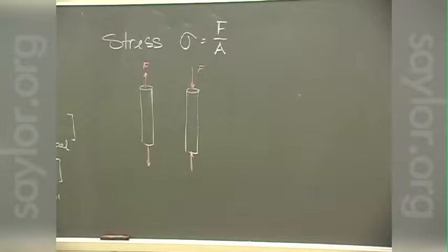For example, wood. Wood is very good in compression. It's terrible in tension. It's a factor of somewhere around 8 to 13 difference. If you're building something, you typically don't want to hang it with wood structural members. If you're going to build a shelving system that hangs from the ceiling of your garage, you're going to want to have it hang from chains or cables rather than from wood straps themselves. Concrete is also that way.